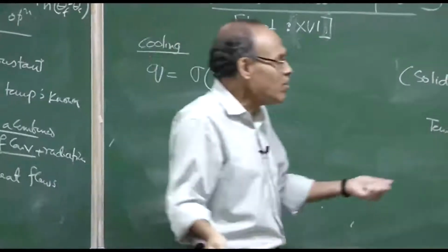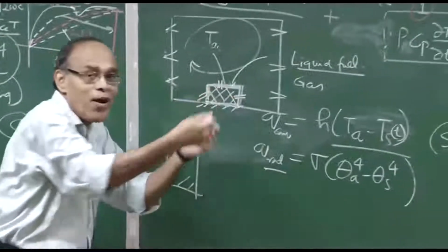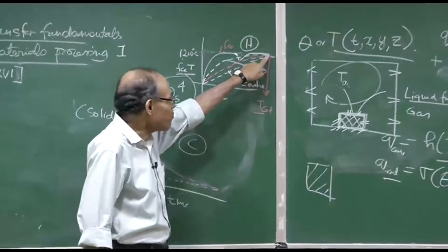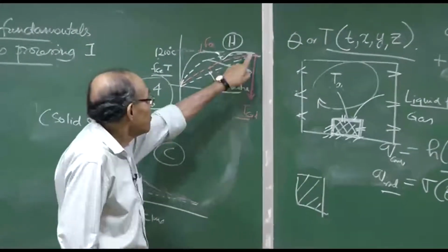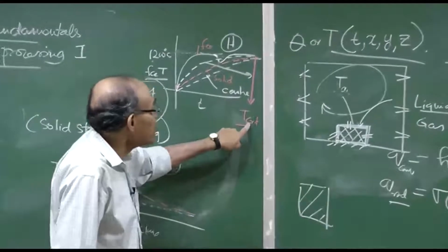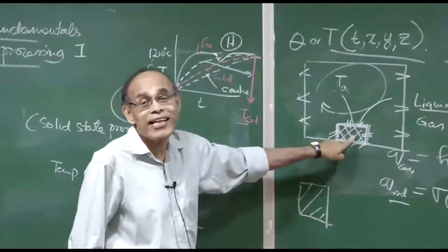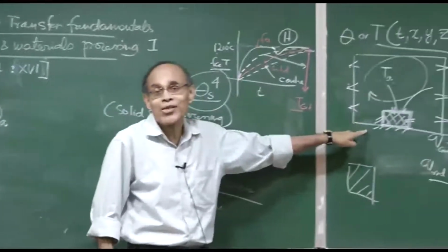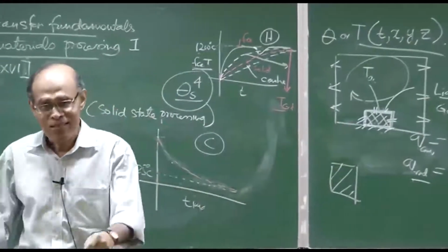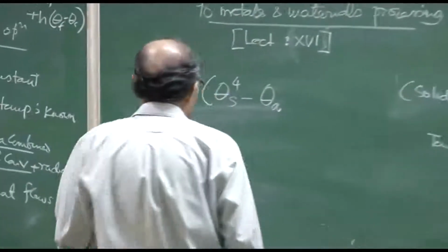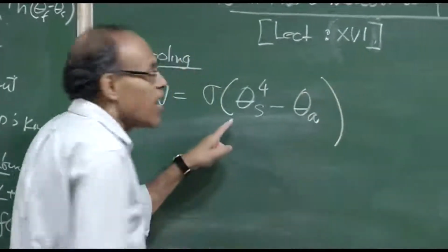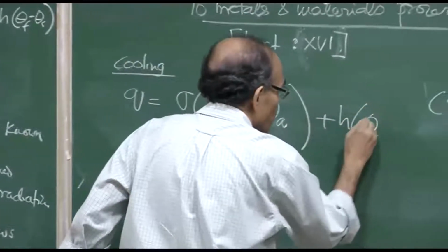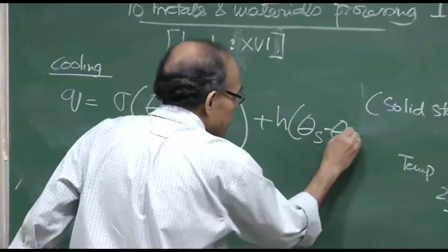The initial condition is known because I have taken it out from the furnace and we had the temperature everywhere within the solid known, which is the temperature arrived at the critical time. So, it has become equal to 1200 degree centigrade. So, the cooling operation starts. The end solution of the heating operation becomes the initial solution for the cooling operation. I have taken it out, and now the cooling starts, and it starts because of this flux being operational, and there is a convection flux also, theta solid minus theta A.